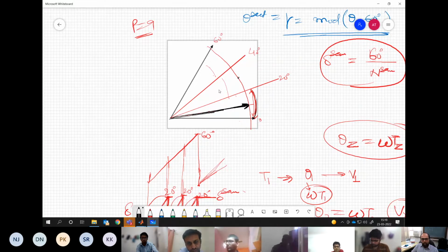Again, the same thing, when you apply the same sequence, let's say 0, 1, 2, 7 or 7, 2, 1, 0, all the way from this point to this point, the resultant vector will be lying in the middle here, because that is what we are computing it for. The T1, T2 dwell times are related to this position. That's why the resultant is here. And the last point will be over here, the last sample.